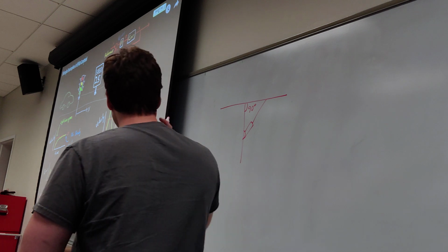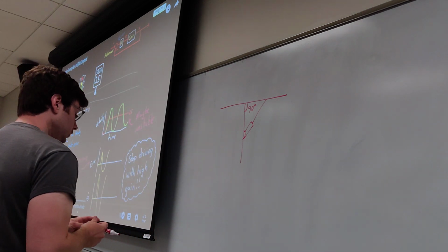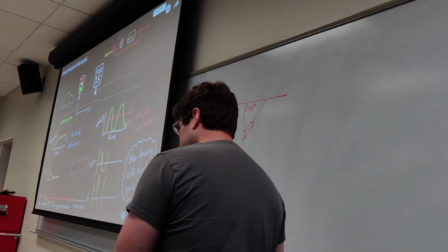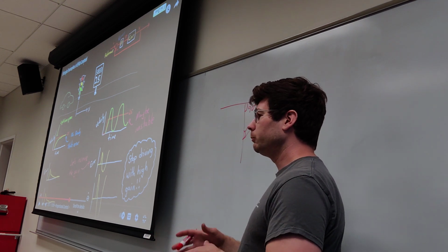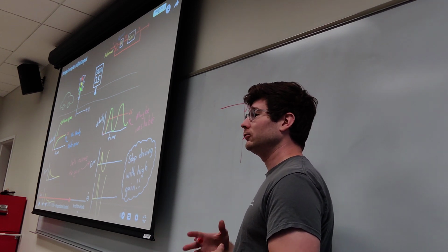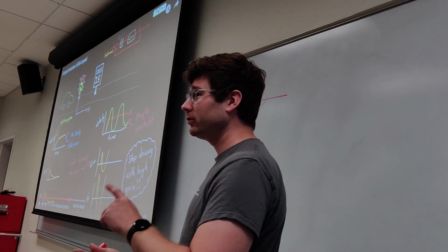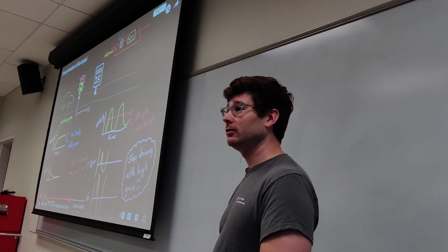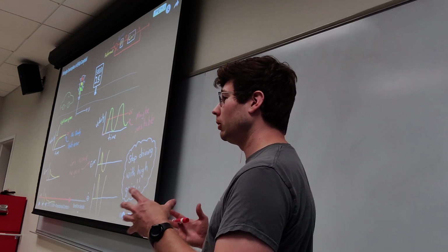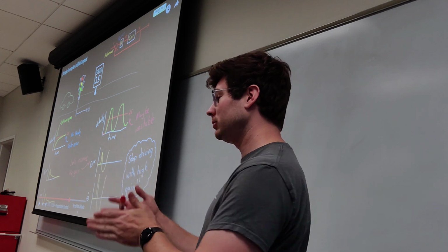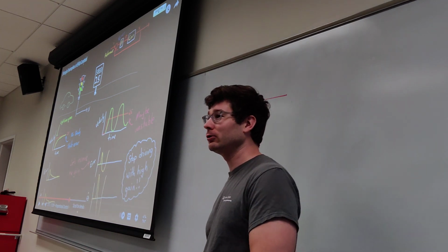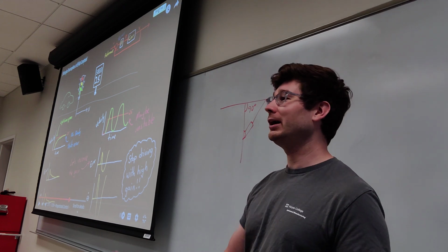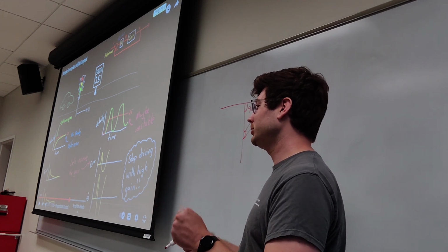Okay, that's the goal. If it wasn't clear, you can use a PID controller. You can use portions of it if that's useful to you. You can use just the P, just the I, or just the D to do what you need to do. Or you could use all three, or even just P and I, or I and D. They're called PI controllers, ID controllers, PID controllers, and all the combinations of those things.